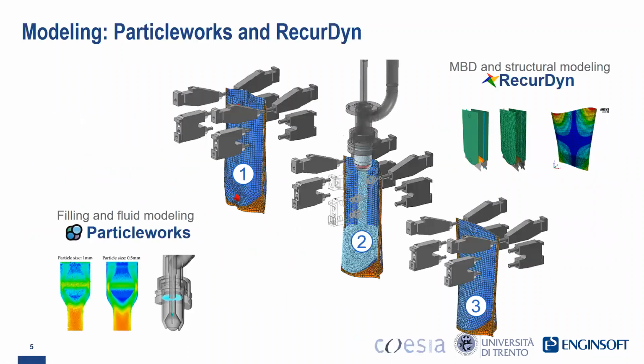So in here is the overall simulation, the co-simulation actually. At the beginning, we have the formation of the pouch, so the opening with also, of course, some friction model and the forces model by RecurDyn. So in this way, we can analyze the stresses on the pouch and the shape of the pouch. Then the pouch is positioned where the injection of the fluid is.